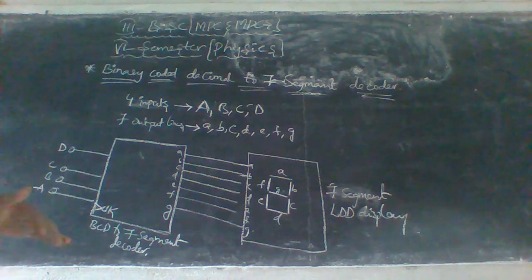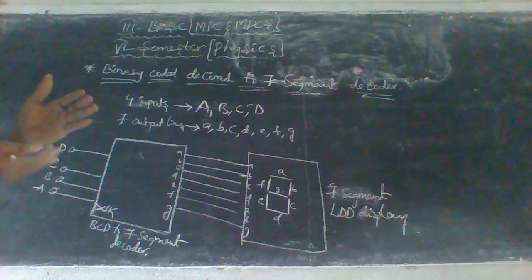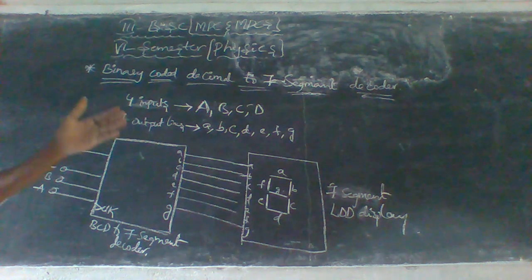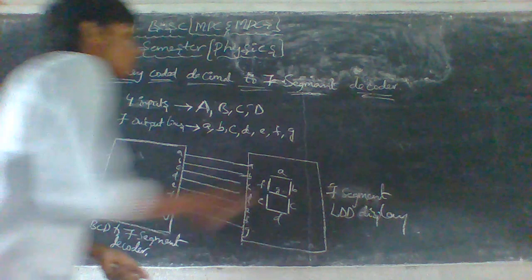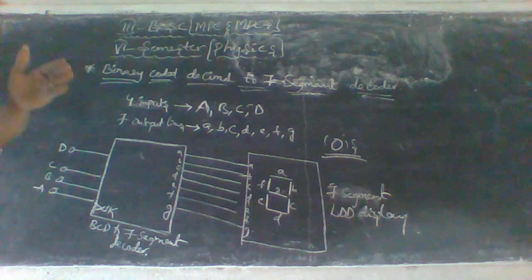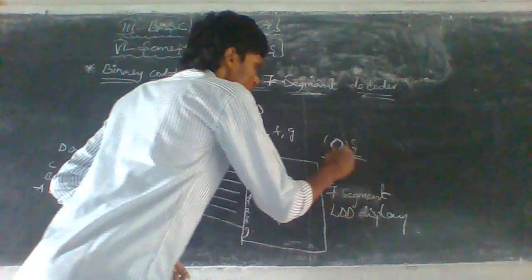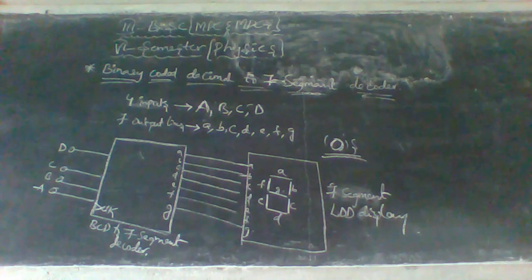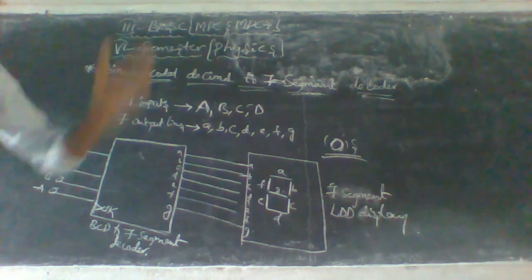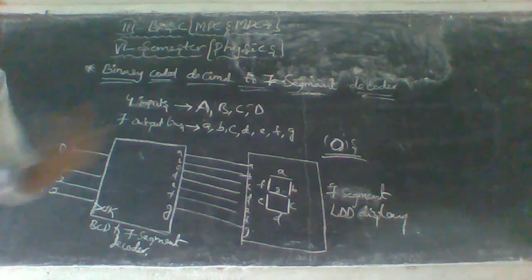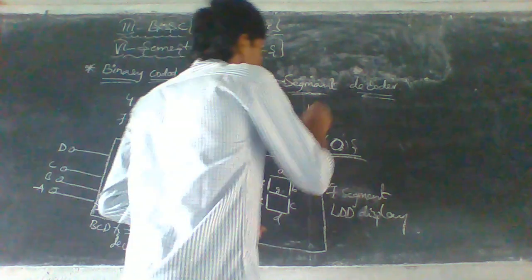For the common anode type 7 segment light emitting diode display, we only have to interchange all zeros and ones in the output set, that is for A, B, C, D, E, F and G. Replace all 1 by 0 and vice versa and solve using the K map.